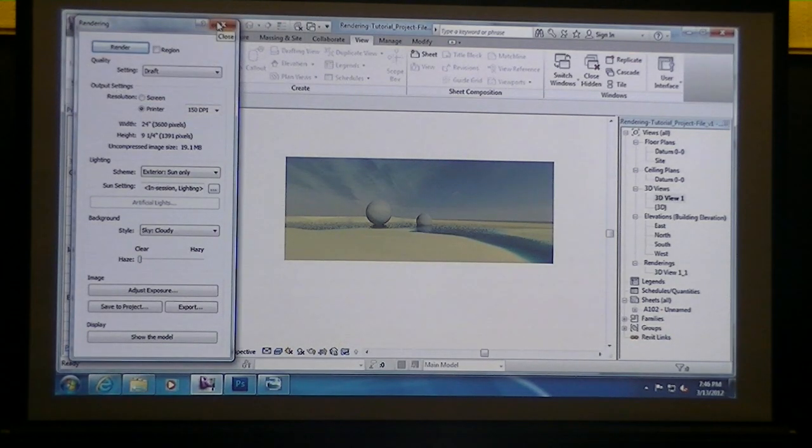One of my renderings you can't really see because I was at an angle where you couldn't see the bridge path, but I actually didn't have the bridge path showing up in that view, and I didn't notice it until I went to my next rendering, and it started rendering, and I was halfway done, and I was like, you don't even see my path because I was looking down on it. That's because it was a mask, and I didn't have it shown in that view when I hit the render button. So just be aware of all those visibility settings when you're working on that.